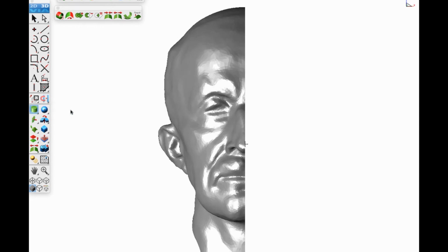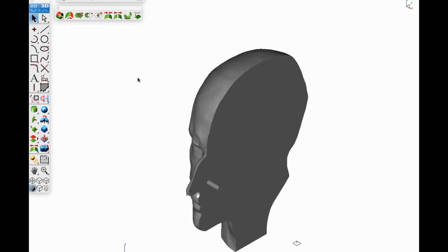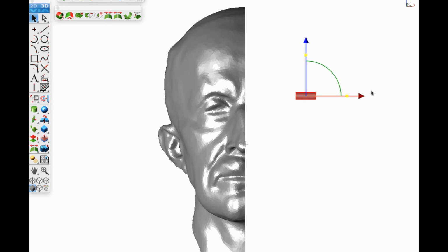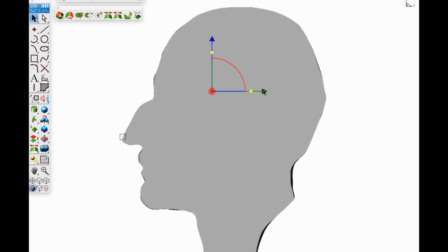I will go to the cylinder tool, cylinder mesh, and we'll make this 0.01 inch radius. And let's place it relative to our part. And we'll create 3 alignment pegs.